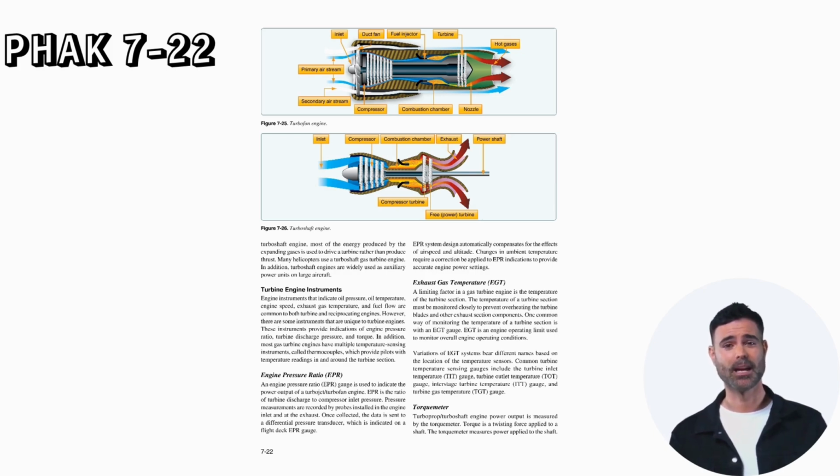EPR system design automatically compensates for the effects of airspeed and altitude. Changes in ambient temperature require a correction be applied to EPR indications to provide accurate engine power settings.